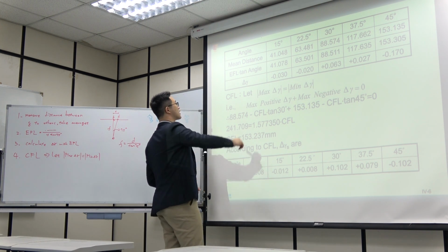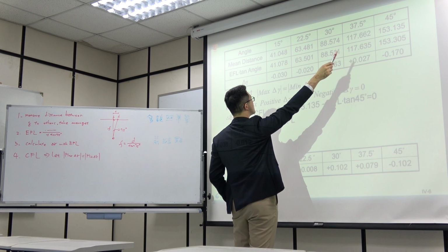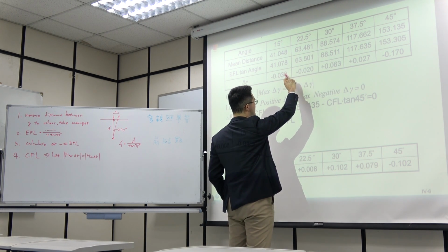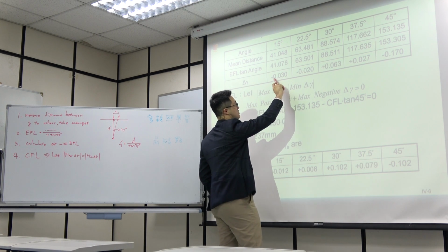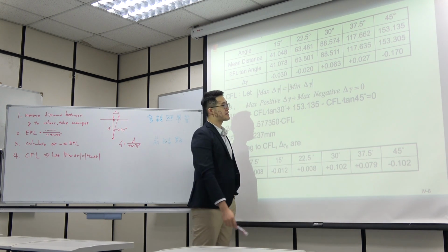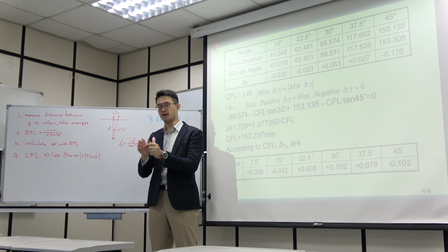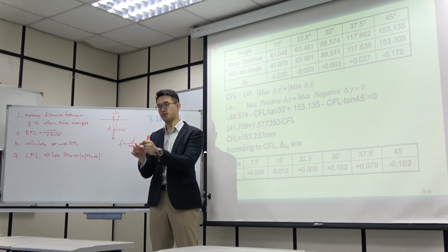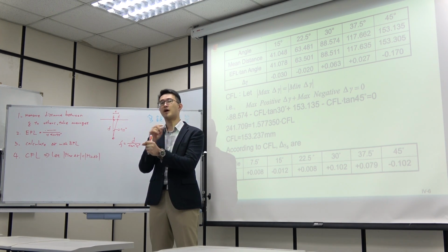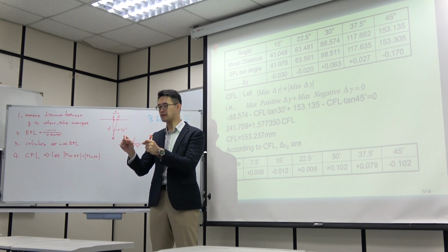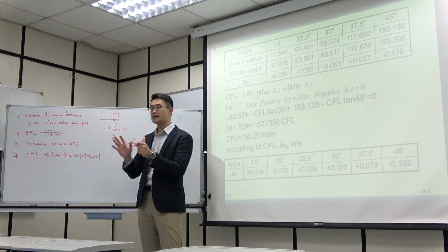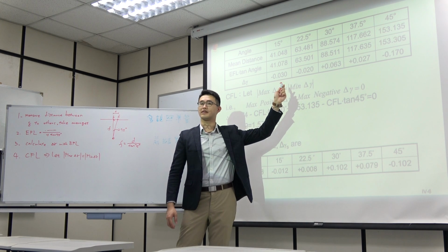As you can see here, for each of the distances we have a different length distortion, and some of them are negative and some are positive. On the image, if you are using the principal point as the radial center, positive and negative distortion means that some of them are away from the radial center, and some of them are negative, closer to the radial center. That's the behavior of the positive and negative here.